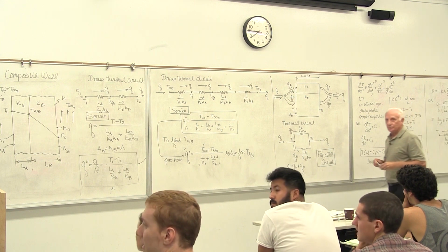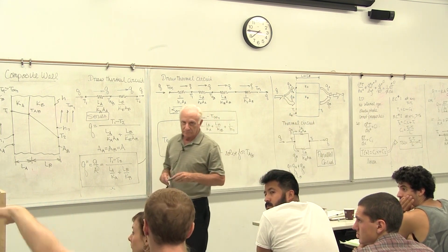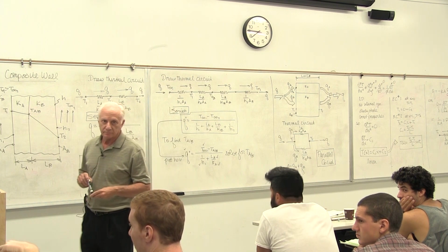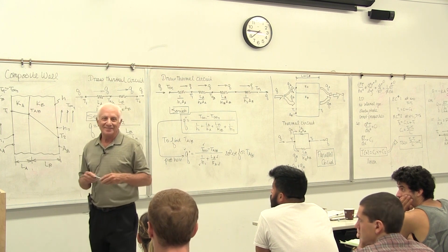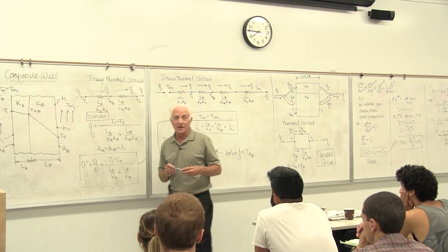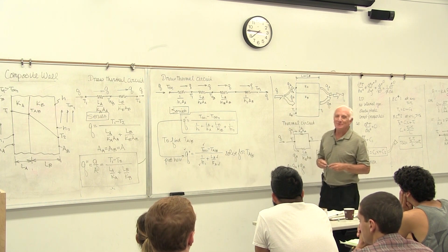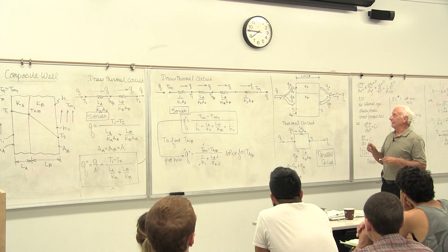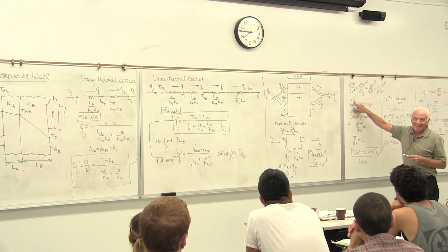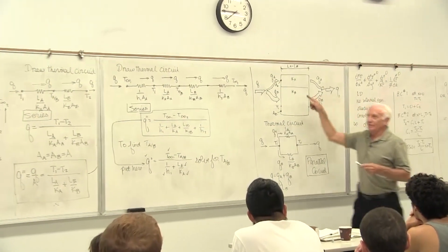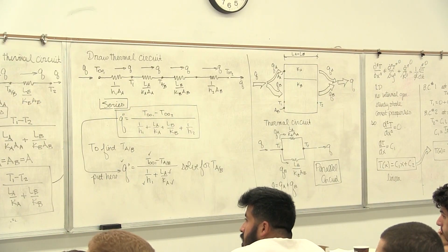Say you had a wall where the concrete comes out a little further than the glass. So you just consider K for the concrete and then do both. Yeah, you have to change that L. When you do stuff like that, though, the problem you get obviously is it starts to deviate from 1D. Even here, do you think that all the heat just goes straight through in one dimension X out there?